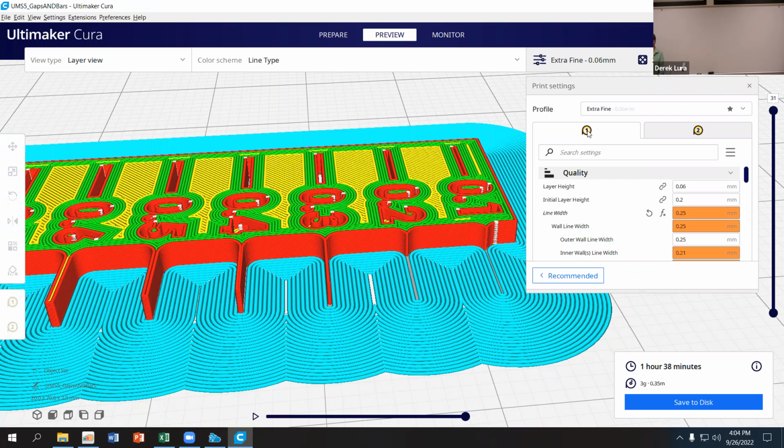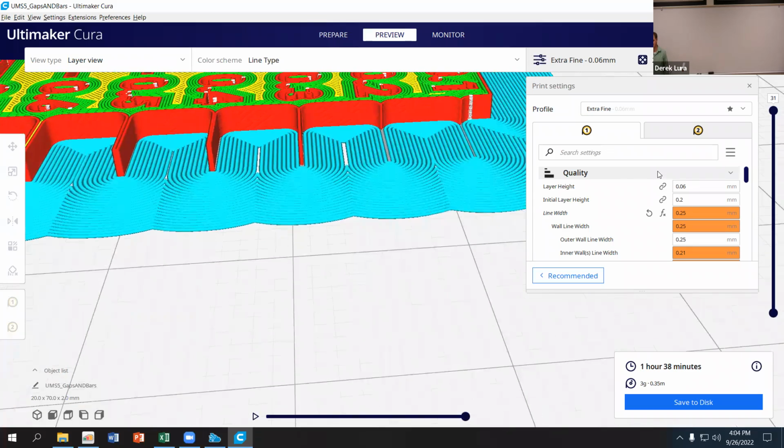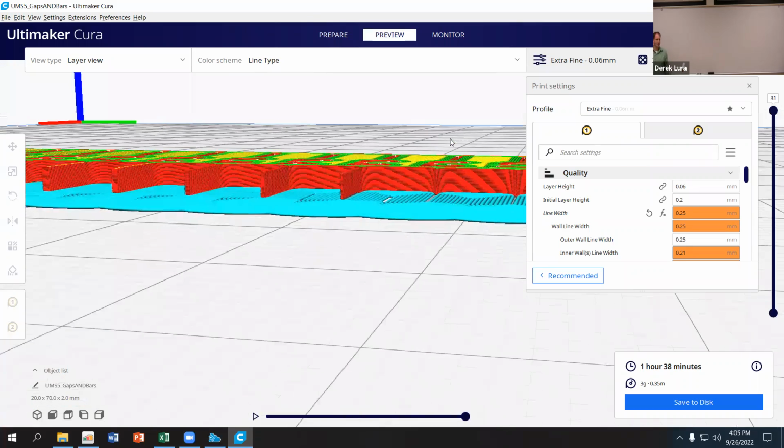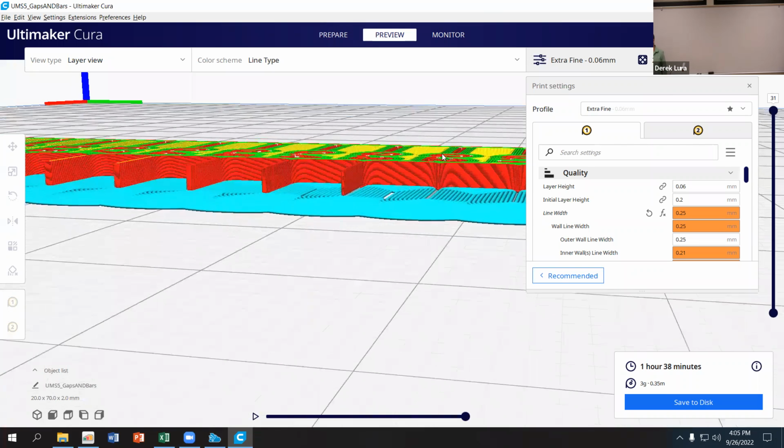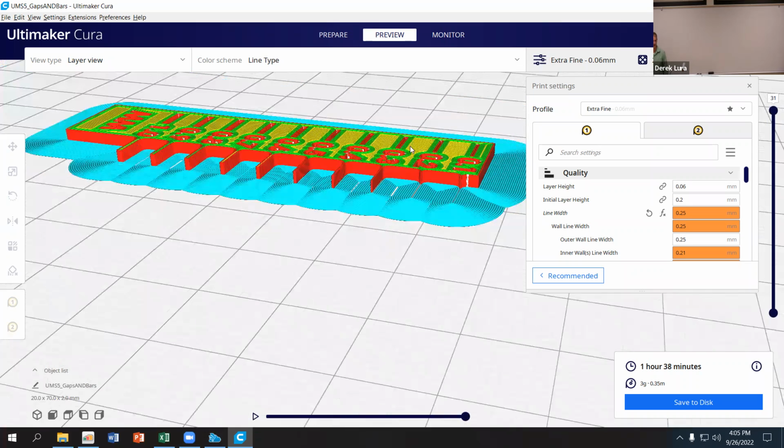But they're always coming up with new ways of adding additives to the plastics. So there's plastics that have carbon fiber filling inside them, and different things like that that can improve their strength. And then you can also talk about resin printing and those kind of things, which use a very similar technique, except for instead of printing from the bottom up, they kind of pull the parts out of the resin, moving the crosshead upwards as opposed to the build plate downwards, right? But it's very similar. And the slicers that they use are very similar to this as well.